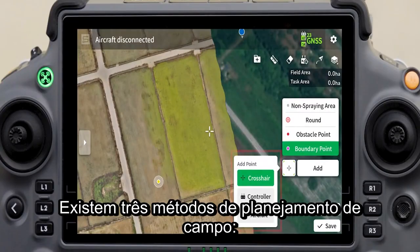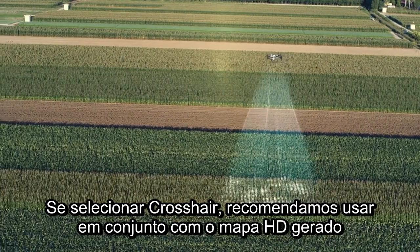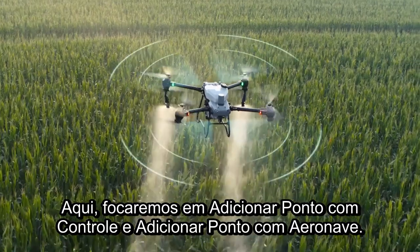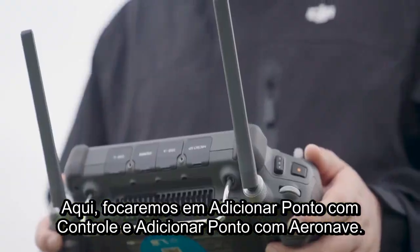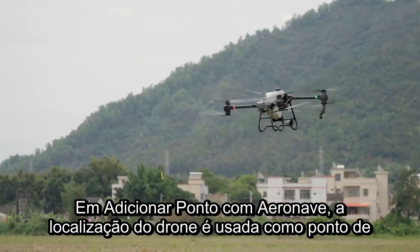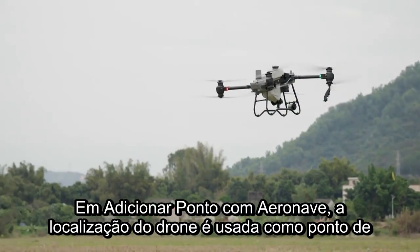There are three methods of field planning: Crosshair on the map, Add Point with Controller, and Add Point with Aircraft. If you select Crosshair, we recommend that you use it together with the HD map generated upon mapping. Here, we will focus on Add Point with Controller and Add Point with Aircraft. If you select Add Point with Controller, the location of the remote controller is used as a reference point. If you select Add Point with Aircraft, the drone location is used as a reference point.